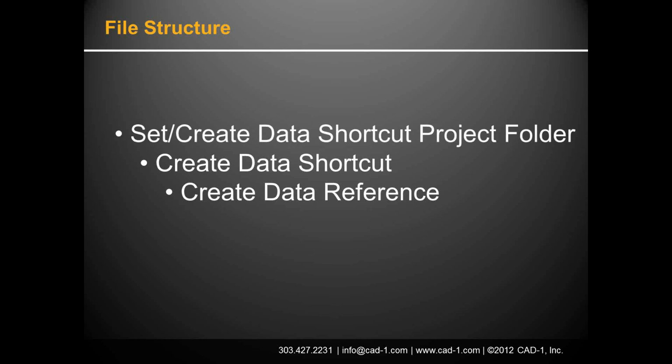All right? And we have a good question here from Lloyd. Lloyd asks, if you remove or delete the source drawing, does the reference remain? That's a great question. So again, this is a reference, very similar to an XREF. So if I'm in a drawing and I'm XREFing in another drawing, what happens if I erase that drawing? Well, it's going to say, hey, I can't find the reference drawing anymore. So it gives me a little warning saying the references are broken. You'll get the same sort of thing in Civil 3D as well, and I'll show you that as we get into it. So a very good question, Lloyd.